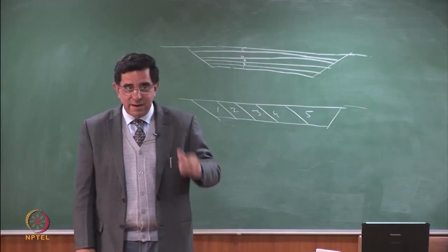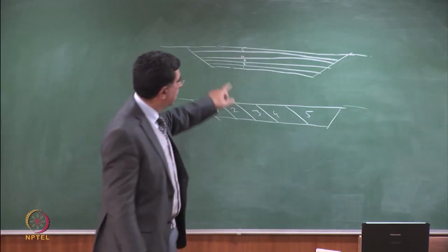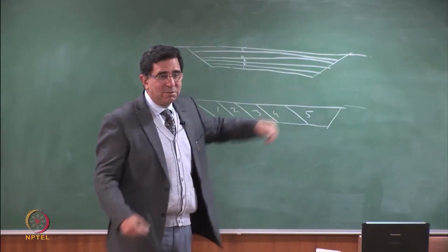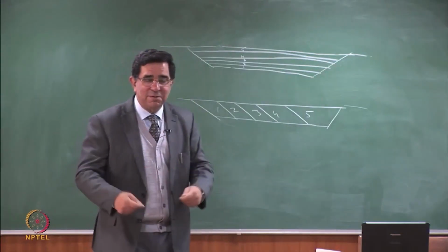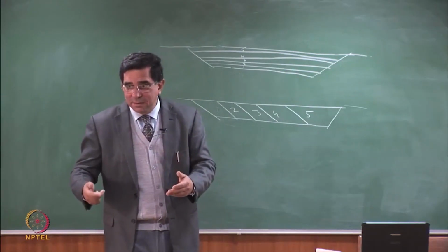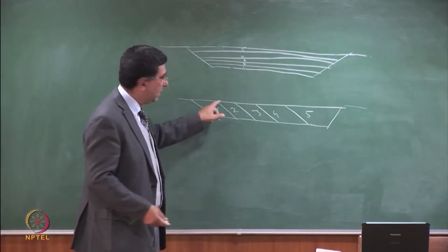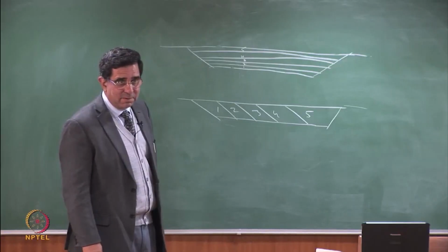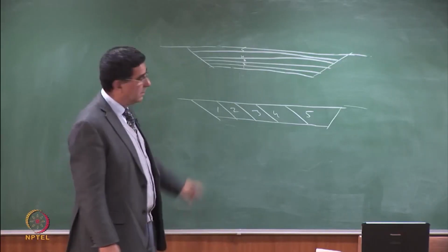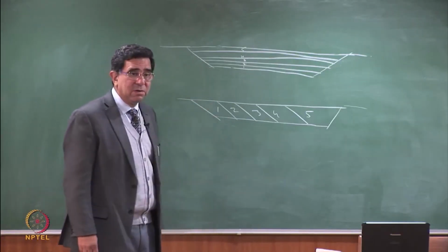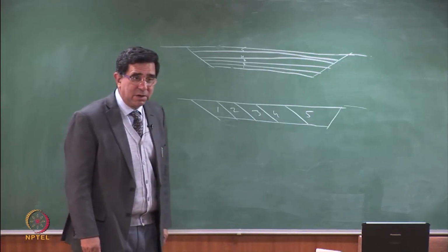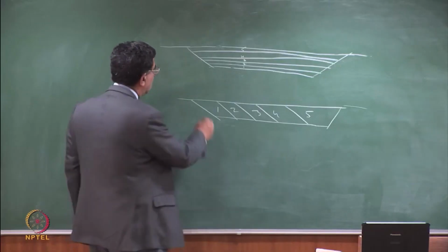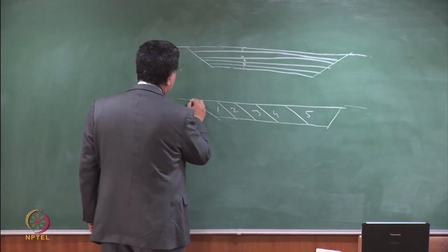And when it rains, I can't put a final cover here. Can I put a final cover here? Because if you are going to put a final cover after every phase, it's going to be very expensive. Whereas I can put a final cover here because I've reached the top. Do you understand what I'm saying? So this allows me to reach the top at the end of the year, and before the monsoon comes, I can put a cover. So this becomes my final cover.